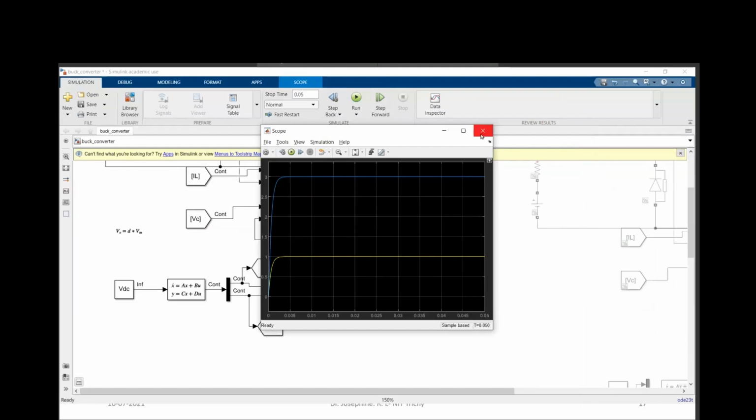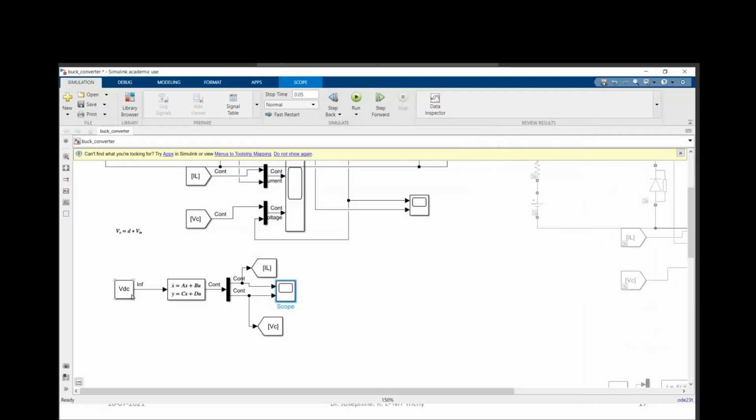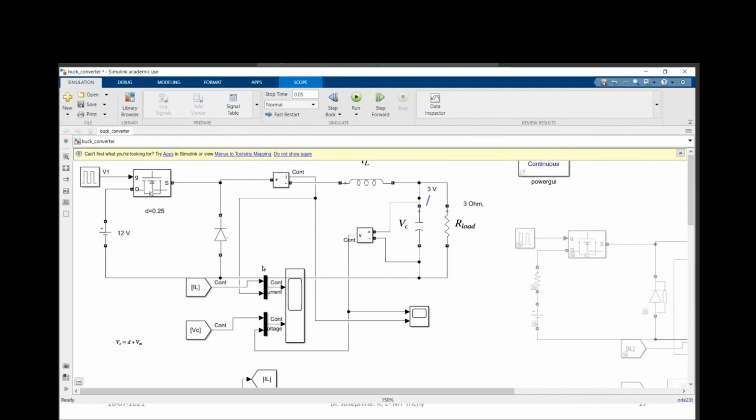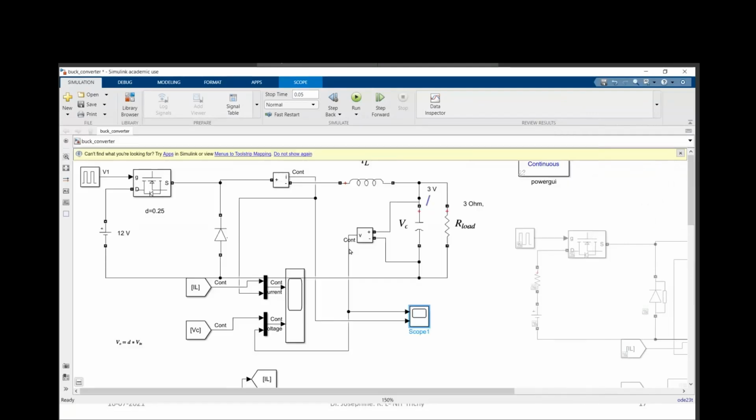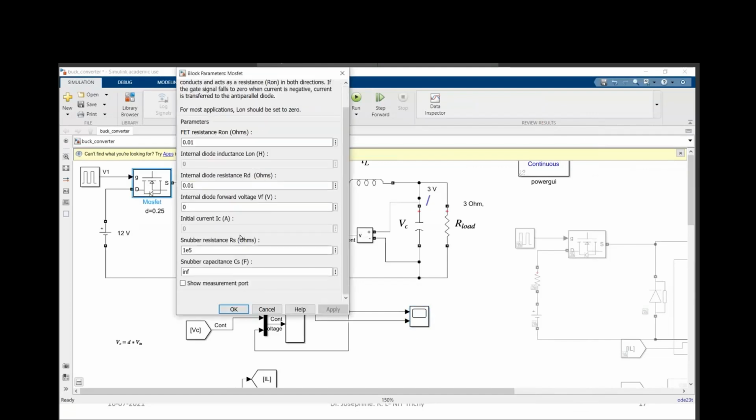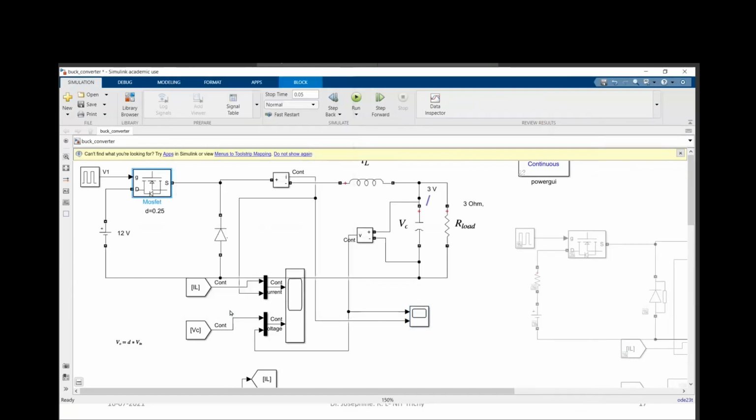It is going to give the exact value because I have given VDC as 12 and I've just used the state space representation and found this. But if you apply it here, you have got a bit less. This is because you're going to use a real circuit here, and because of this, even the on-state resistance matters.